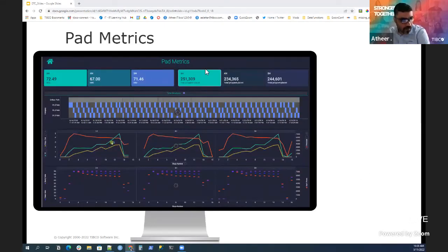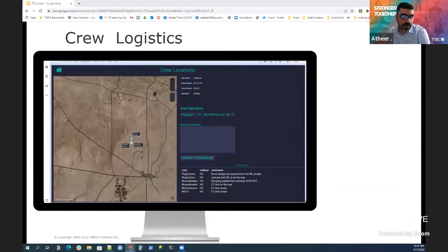And then in here, you have an idea about your material consumption and time usage analysis, where it gives you a comparative idea among all the wells that you drilled, how much material you used, for example the propellant you used and the friction reducer materials that you used, to have an idea where you had an anomaly, or where you overused some of the materials.